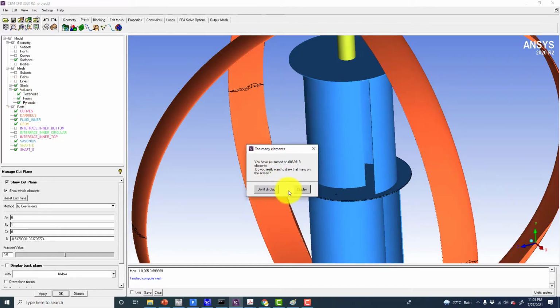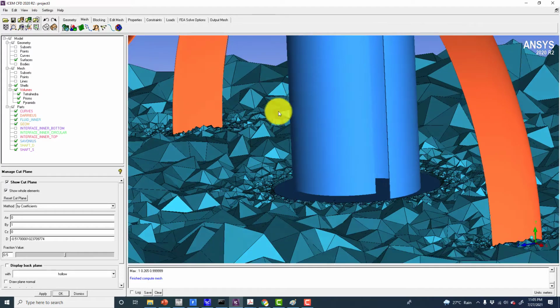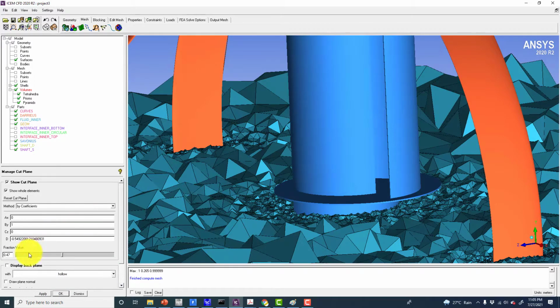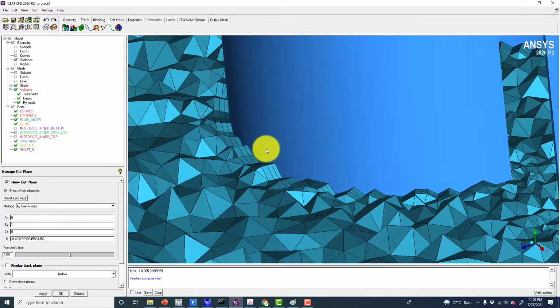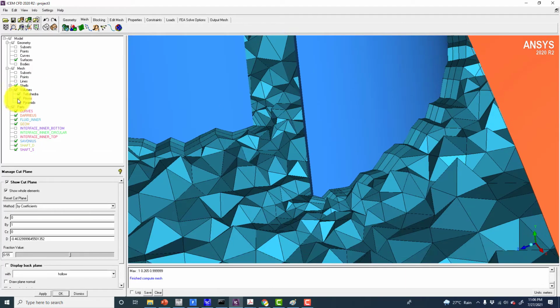But anyhow, I will first check the mesh, especially the prism layers, and let's say I display them at 0.47, so it will be a little on the downward side, but we will see the mesh properly on the geometry. Or you can even go, let's say, to 0.55 and apply. Okay, this is okay, and you can see that we have these prism layers, and in some locations where the angle is sharp, we are getting some pyramids, and this is not wanted here.